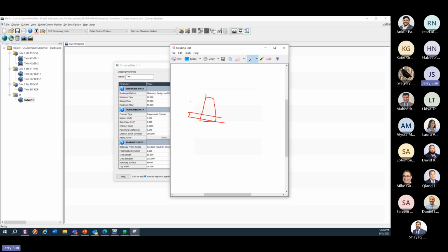But in some areas, if the upstream and downstream drop a lot and the slope is large, we could design a curved bend, and then bend the whole pipe there. In most cases, if it is shallow, we can use manholes.